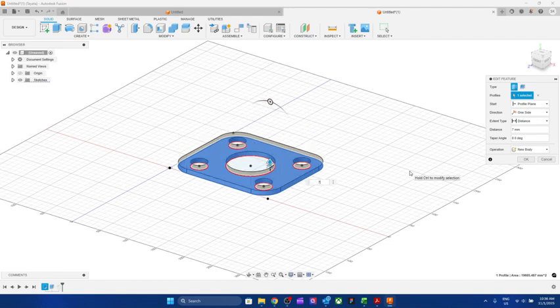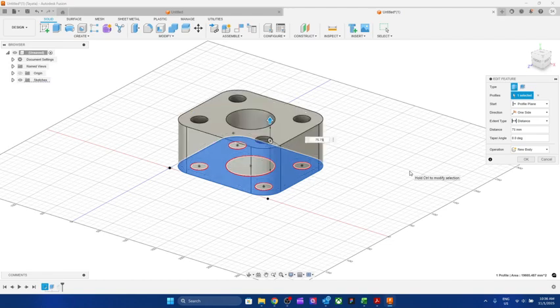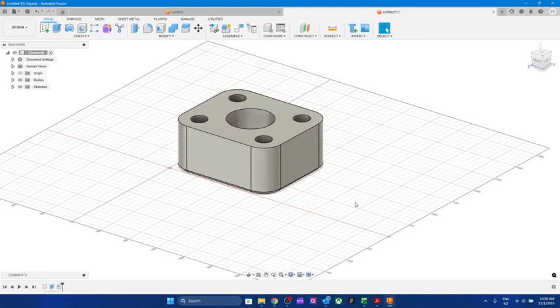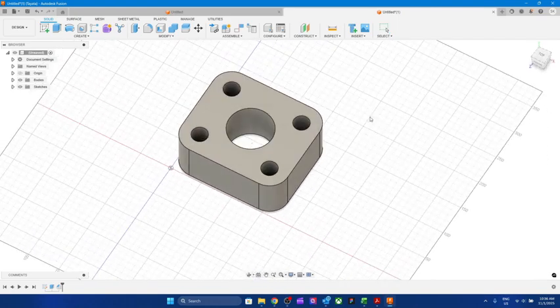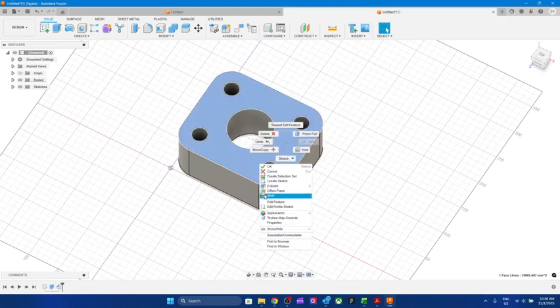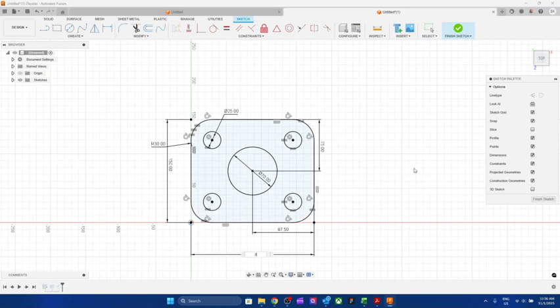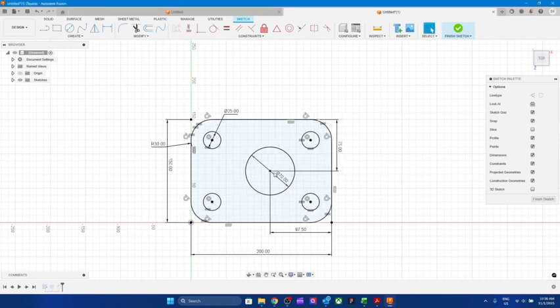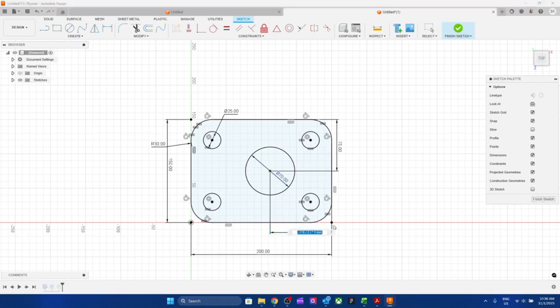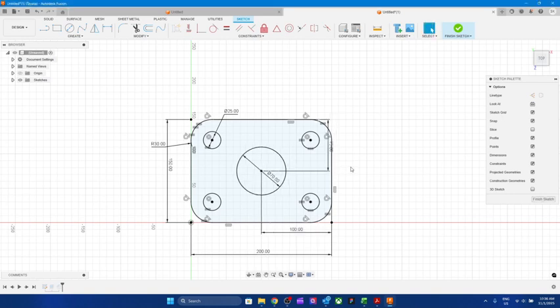That's one thing. So I want to change it to 75.75, enter. Okay. I decide no, actually I want to change more. The original sketch I want to modify. Then I'll simply right click here, edit profile sketch is this one. See, edit profile sketch, I'm going back and now I want to change it to 200. Of course, this circle has moved out of the center, so I'll simply change this equation to 200, enter, and it has worked, 100, 200, and so on.